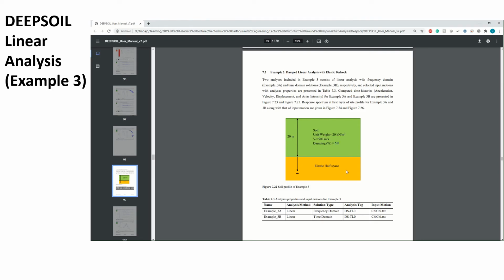We are moving towards a more realistic interpretation of the soil behavior. Still, we are talking about linear analysis, so it cannot be an accurate representation of the dynamic behavior of the soil, because there's not been any change in the values of the shear wave velocity or the damping ratio with the deformation. That's a simplification of the reality.